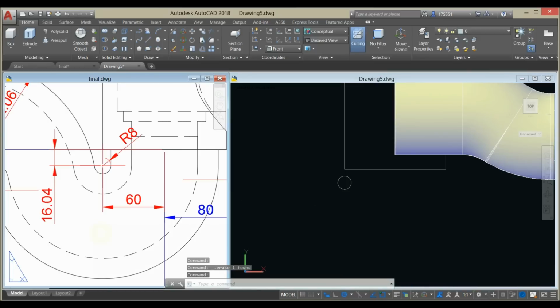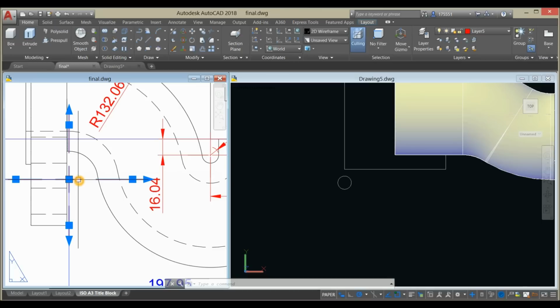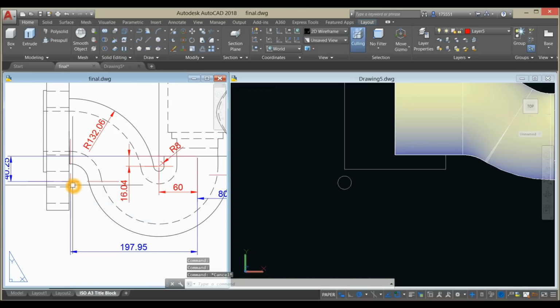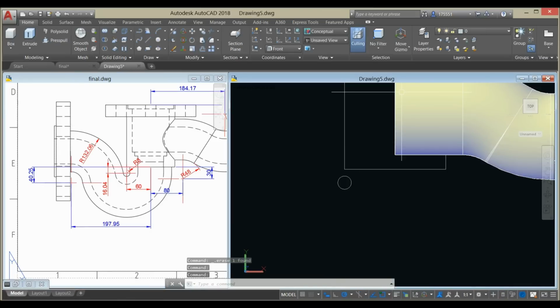And another circle that I should create is this one here, this arc, and the center of that arc is this point, and the distance from the midpoint here to the center of this arc is 197. So I'm just gonna draw, I'll bring this back to layer 1.